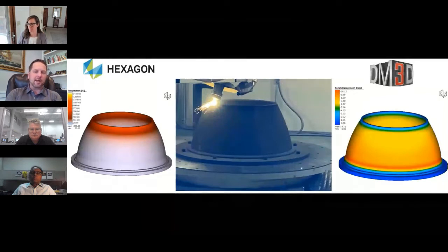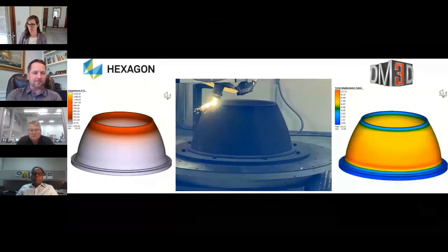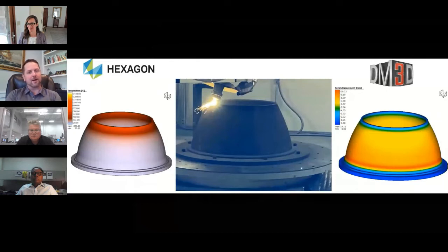So running this on a layer-wise basis, where the entire layer is applied at one time, this simulation solved in about 48 hours for a thermomechanical, whereas the physical process took 96 hours. So it solved in half the time of the physical process. Now, of course, if we go down closer to being a transient process of capturing the individual scan vectors, that could go up significantly. But simulation is probably the number one challenge that we face, and it's still the biggest hurdle that we're working towards.